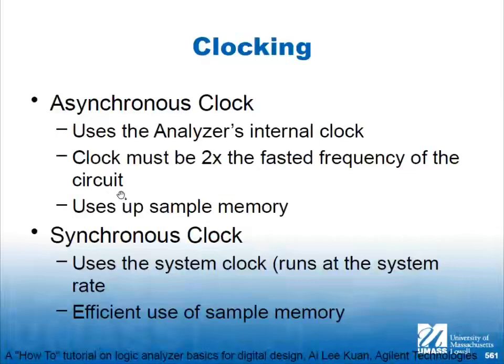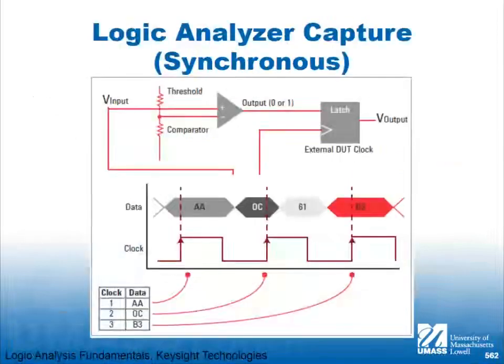So in logic analysis, you want to bias yourself towards a synchronous clock. I only use asynchronous clocks in oscilloscope measurements, but I try to always use a synchronous clock when I'm doing logic analysis. All right, we're only doing logic analysis, sorry, in the FPGA anyway. So very simple, right?